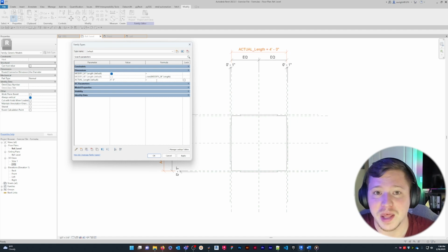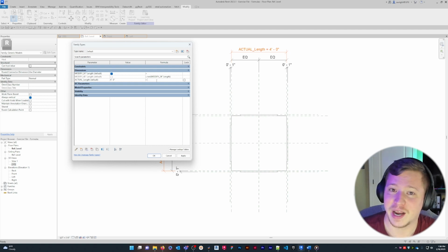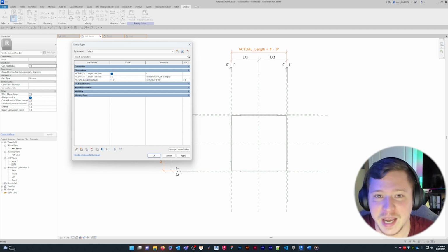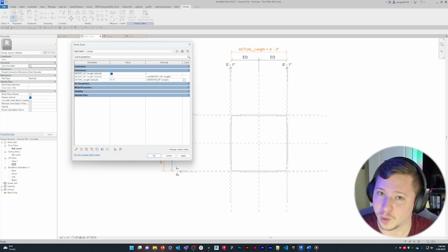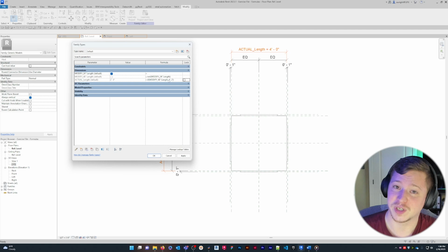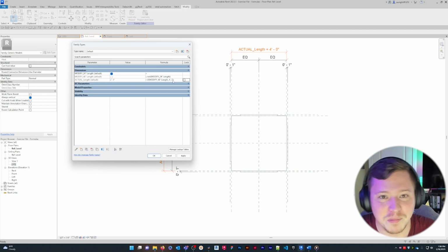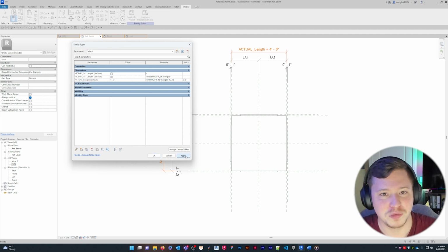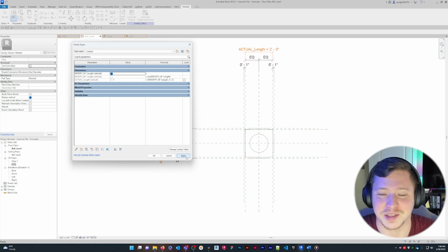Next, we need another short formula that takes our radio buttons as input and outputs a specific length. That formula is written like this: if(modify 48-inch length, 48 inches, 24 inches). Essentially here we're saying that if this condition, modify 48-inch length box, is true, then the length is 48. Otherwise, or our false statement, it's 24. Paste that back into the formula box for actual length and give your radio buttons a try. The cube should flex between 24 and 48 inches at the touch of a button.